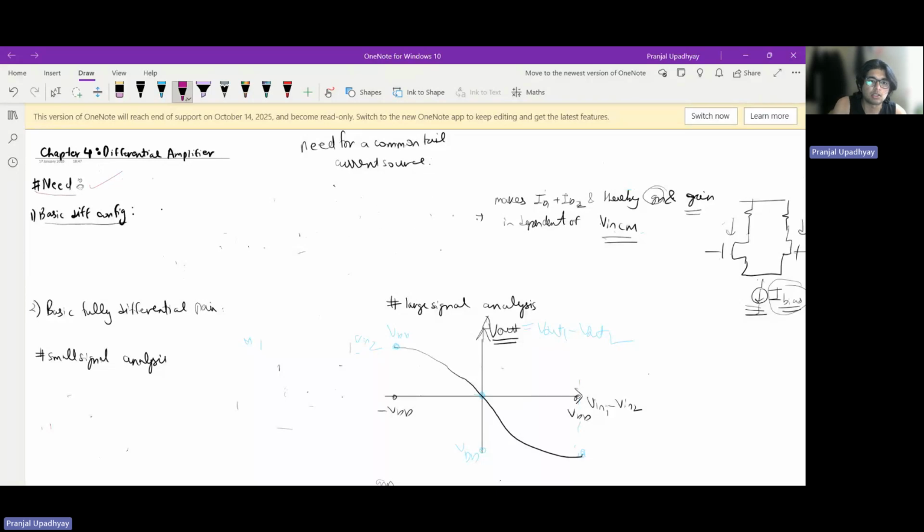and here I would just recall, which is also given in Razavi, that if you sketch a basic differential amplifier, in this case this is actually a pseudo differential amplifier where we are not having a common tail current source to tie these two ends together. So why is this not used as such? It is not used as such because here the GM is a strong function of the common mode signal, which is basically the bias signal, which is something we typically don't want, right?